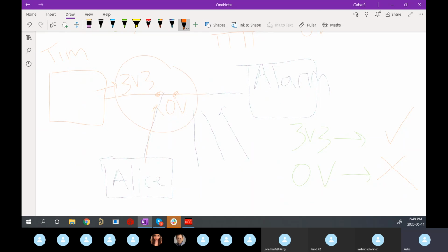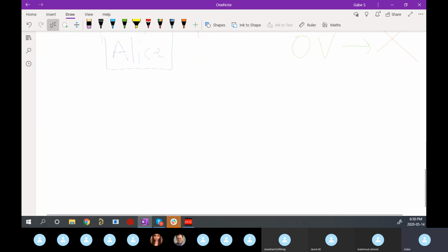And so where we thought we made a super safe system, in the sense that we had 2 people who could alert the system that there's a fault, now all of a sudden we've created a short. Everything catches fire, and our safety system accidentally killed everyone. No bueno. And so people invented open drain. What open drain allows you to do is rely on your pull-up resistors.